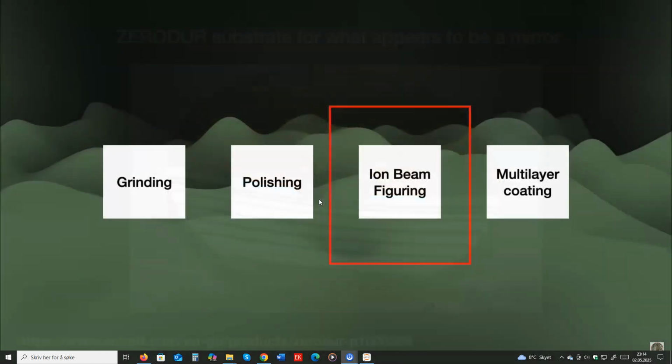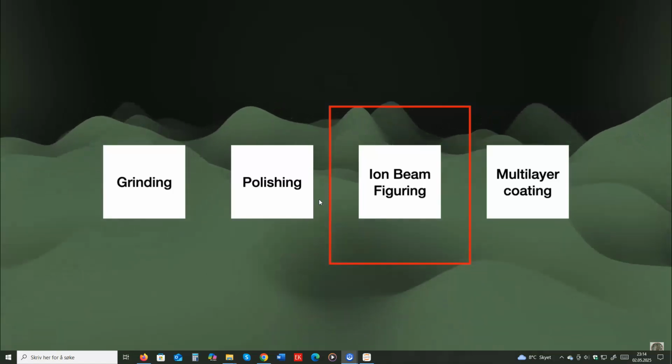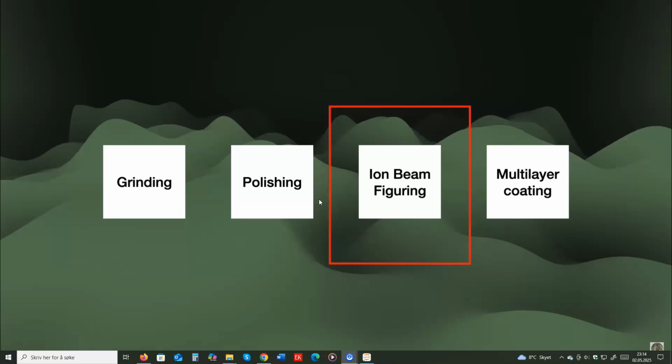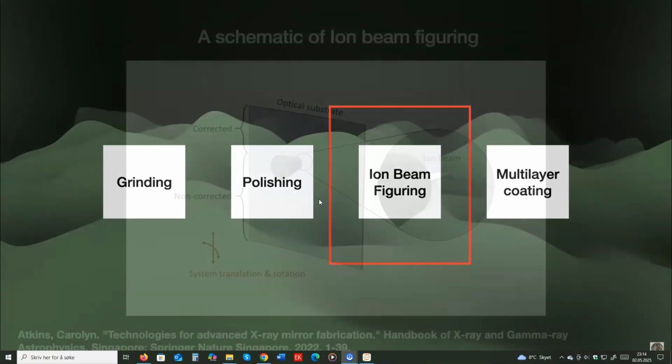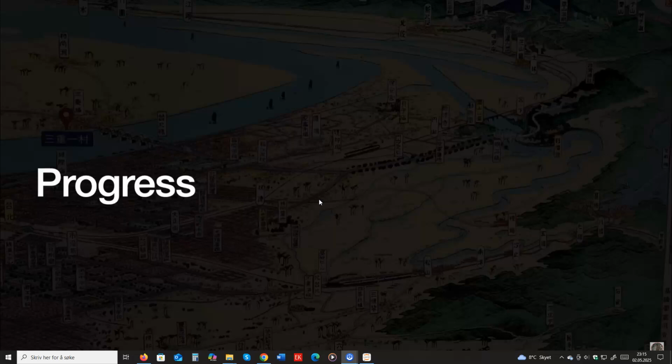So, to the existing polishing steps, Zeiss added another subtractive process, ion beam figuring. Ion beam figuring is where we accelerate the ions of inert gases like argon towards the mirror surface. Ion impacts cause atoms on the surface to sputter off into the void, essentially letting us polish the surface layer atom by atom. And throughout this process, you're doing metrology. You cannot fix what you cannot see. Sub-nanometer metrology was the second breakthrough to help make this mirror possible. Throughout the years, ASML and Zeiss showed steady, progressive improvement in eliminating defects.